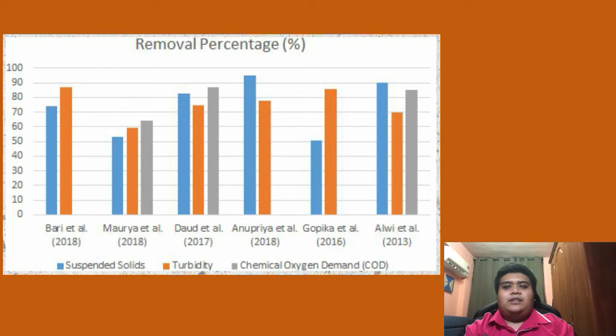amount of suspended solids. This was important because palm oil mill effluent contains a high amount of suspended solids and has a high value for turbidity. So as the banana stem is able to absorb the smaller particles in the wastewater sample, the smaller particles will then settle down in the wastewater sample, which will cause the reduction of turbidity value.